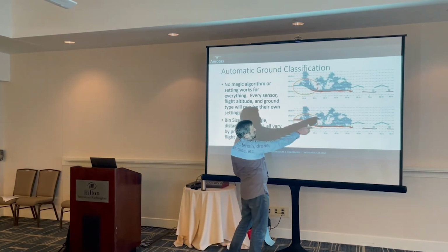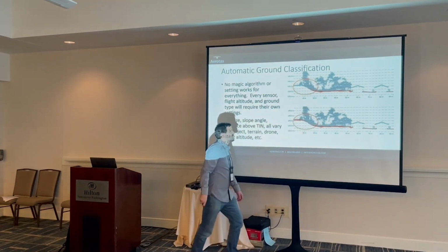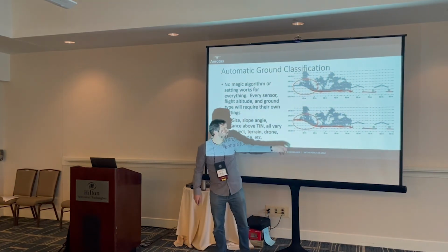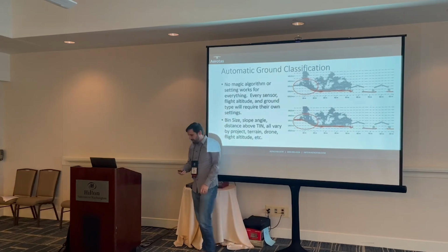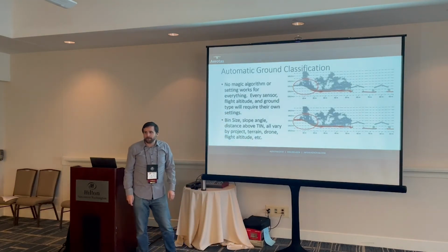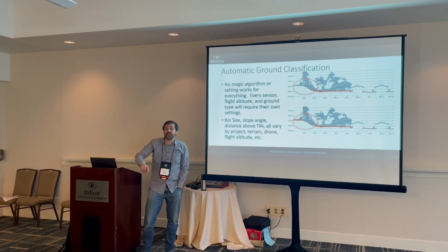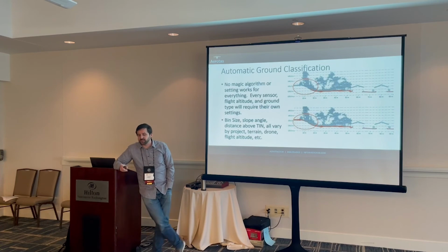This one is just an example of two different settings that you can have to allow for some steeper terrain. That one doesn't like the steeper terrain, that one does. The same piece of software produced both of those, just with different settings. And that's what it is. And like with photogrammetry, there's no magical setting that works on all sites.